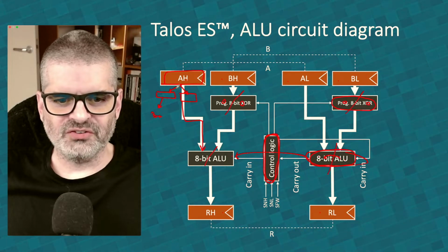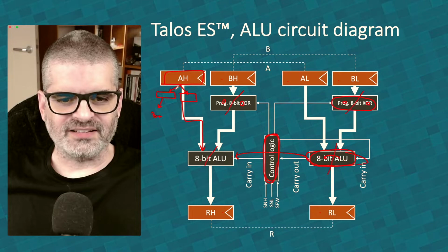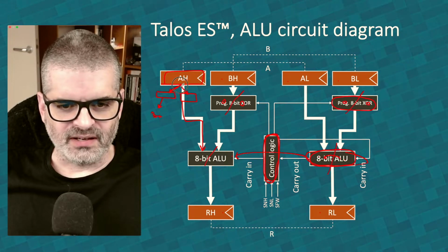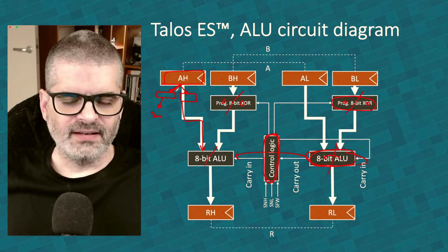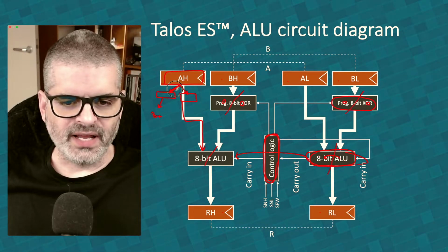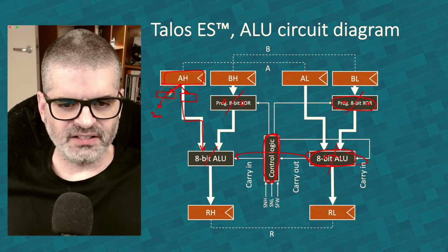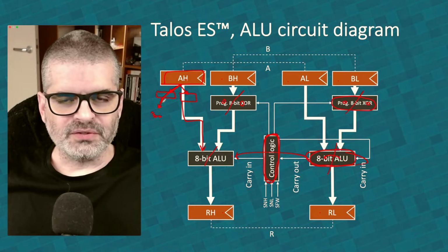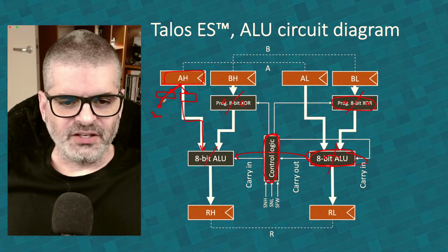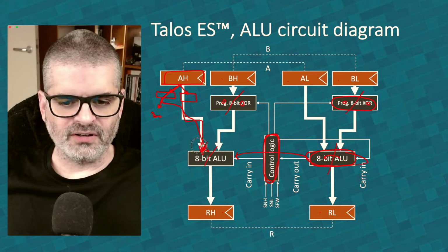You don't want any single chip to drive LEDs and drive logic, because when you're driving LEDs, you will be draining so much current from the pins that are driving the LEDs here that the voltage levels may fluctuate, and you can't take them as valid logic inputs for another chip.